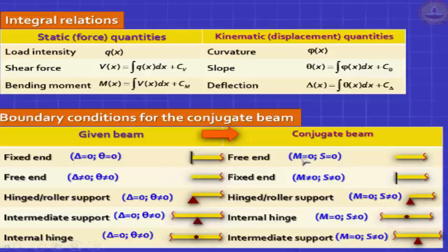So, when will you get a situation which will guarantee that always your bending moment can have a non-zero value? Can have. It's like your bank account. It could be 0 also. No, bending moment will always be 0 and shear force will always be 0. This will happen only in a free end. Always in a free end, unless you apply a concentrated moment or shear force here, which will never happen in the conjugate beam, because the loading on the conjugate beam is your curvature diagram. There are no concentrated loads ever going to act. So this is satisfied. So it's very easy to remember.